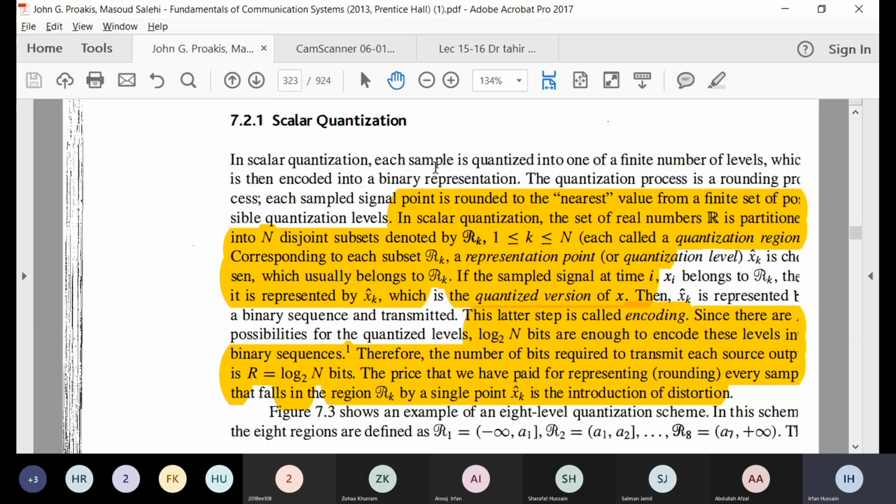So each sample is quantized onto a finite number of levels, a finite number of magnitudes. And then the second process will be that once you have these finite amplitudes, you encode those finite amplitudes into binary representation. But that you will cover in encoding. Here you will just be emphasizing converting continuous amplitudes to a finite number of fixed amplitudes or levels.